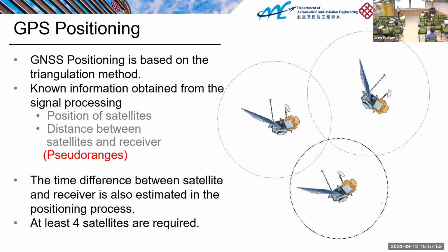You have 4 squared distance equations, right? For one satellite, you have something like x_s minus x_receiver and so on, giving 1 equation. So 4 satellites provide you with 4 equations to solve the 4 unknown variables x, y, z, together with the clock difference between the user and the satellites. Basically, this is the overview of satellite positioning.